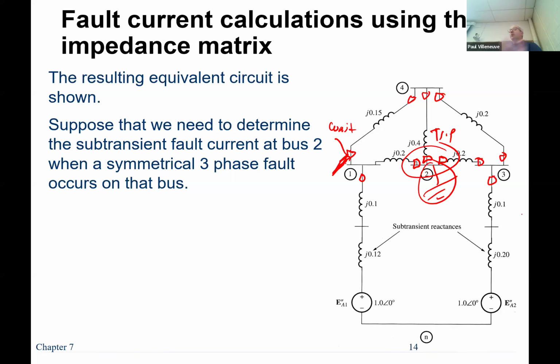I will. You literally got to walk the whole line, right? He's going to go and walk the whole line because that breaker tripped. He doesn't want to close that breaker and say, oh, there's no problem. The breaker opened. Is he going to say close the breaker in? No, you don't know where. You don't know where. It didn't happen on that line, but he doesn't know that.